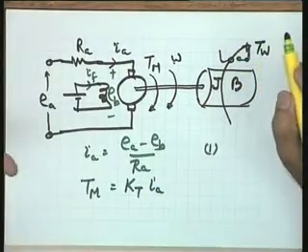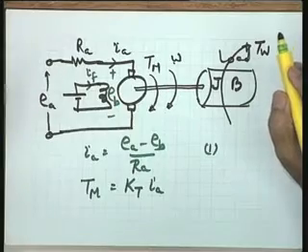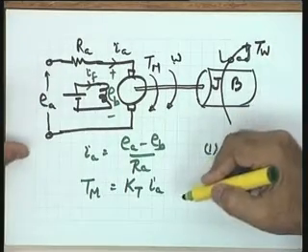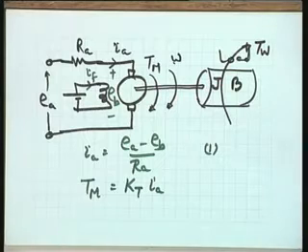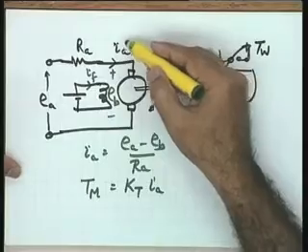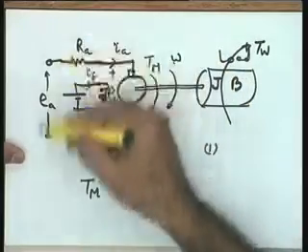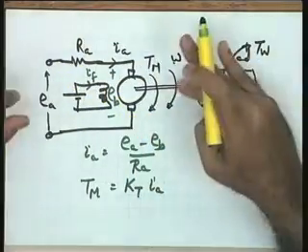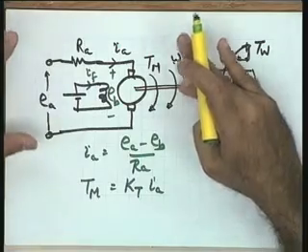of the motor. Please note, Kt is the torque constant of the motor, and this has come this way because If, the field current, is constant and it is an armature controlled motor. That is why the name is given, because you are controlling the armature current through Ea and the field current is held constant. The speed of the motor is being controlled by controlling the current through the armature.